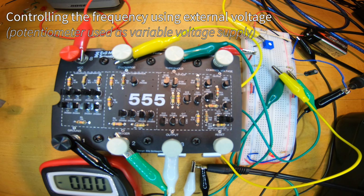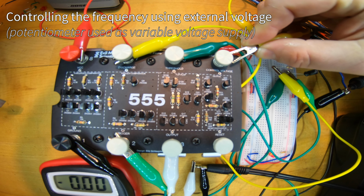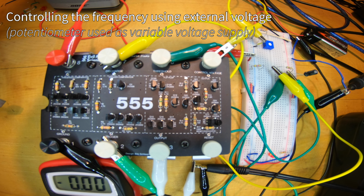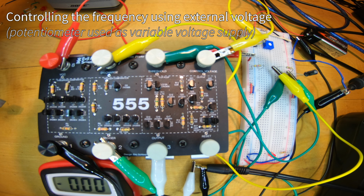Alright, let's take that pot output, which is on a second yellow cable, and plug it into control voltage. Hear the pitch change. And loose connections are going to make it wobble around. So it's often important to solder audio circuits.